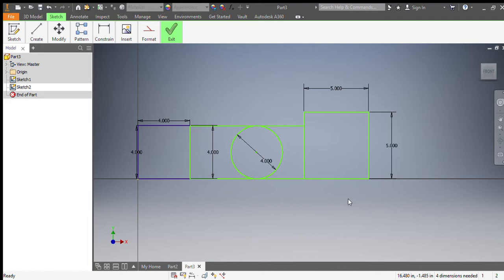So I want you to imagine that your sketch 1 is on a clear sheet of paper, okay, and you wrote on it yesterday. And then today, you grab another clear sheet of paper and you put it on top and you start creating sketch 2. But when you need to go delete something in sketch 1 or erase something in sketch 1, you can't. Okay, the only thing you can erase is the object in sketch 2 because that's your top piece of paper.